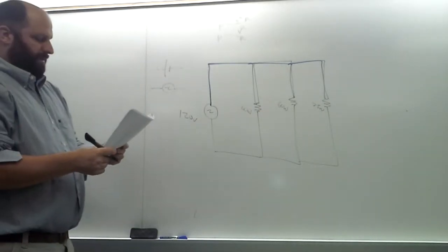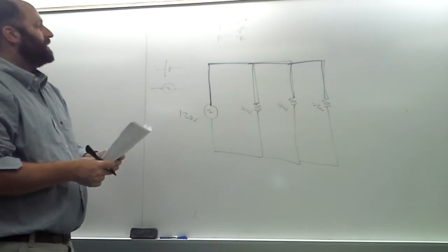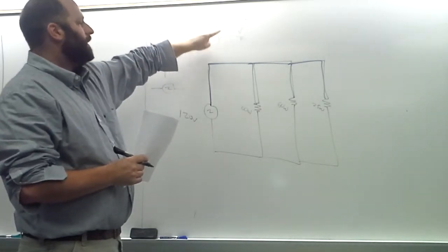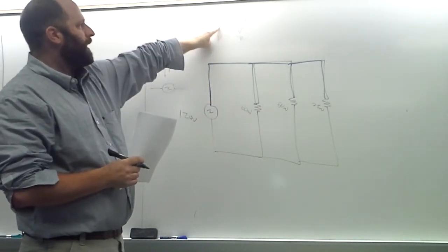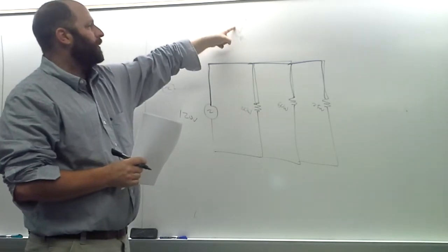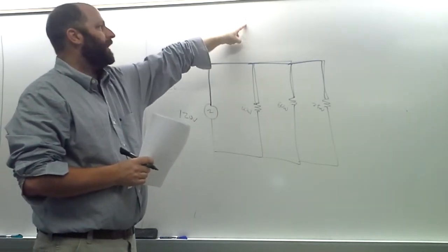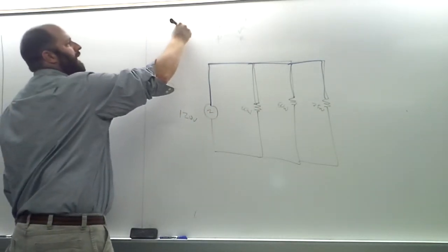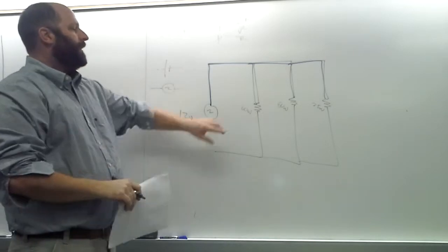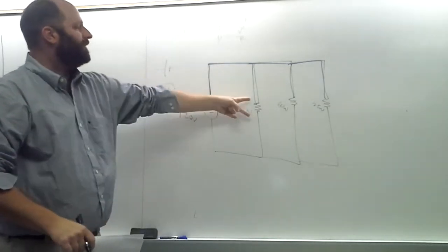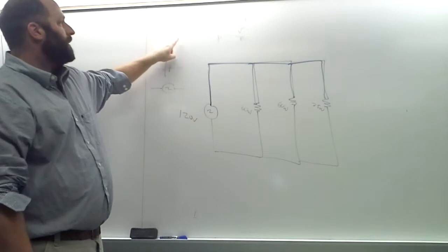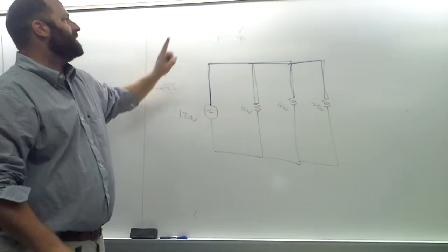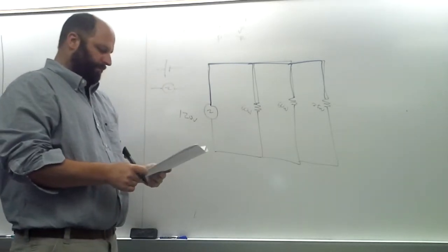Once you know the current, part B says find the resistances. Well, there's a couple ways to do that. Take the 60 watts, put it there under power. Take the current you calculated, put it there. Don't forget it's squared. You can calculate the resistance like that. You can also get it from Ohm's law. V equals IR, remember? So going back to this resistor, I can take the 120 volts, put that value there. Remember, you calculated the current for part A for each bulb, so you can put your current there and find the resistance out. Either one will get that done.